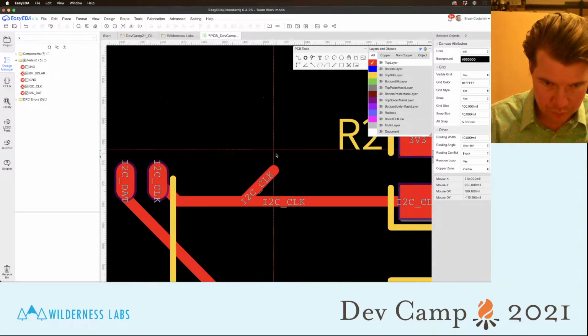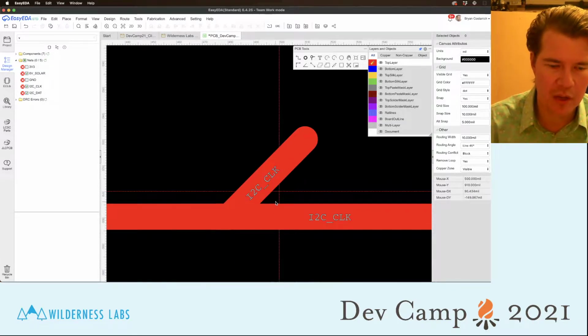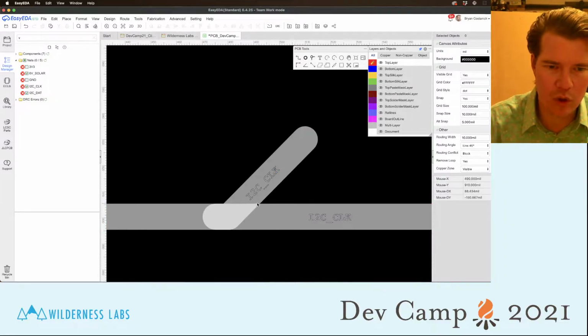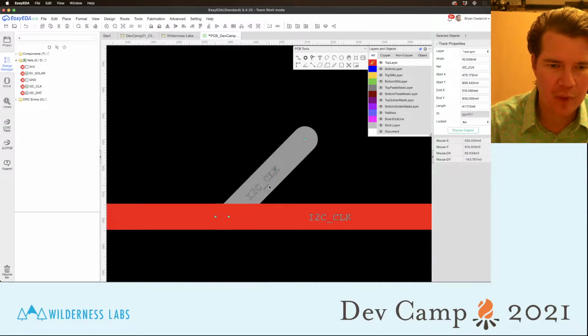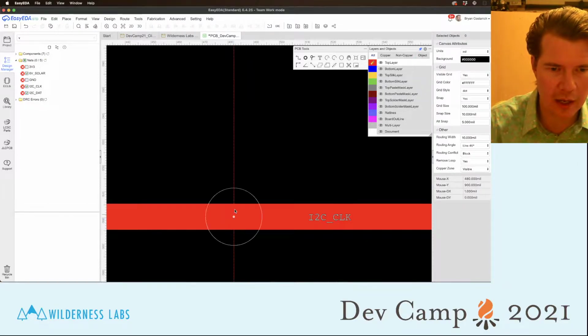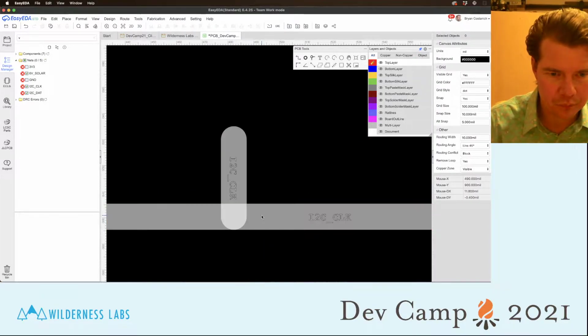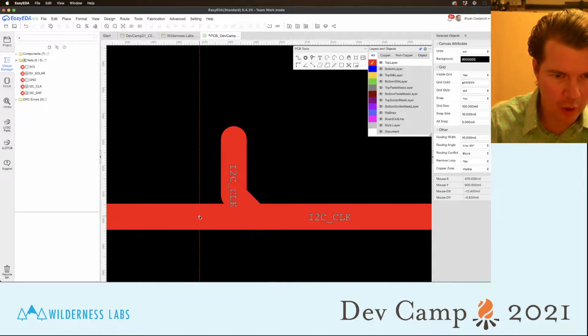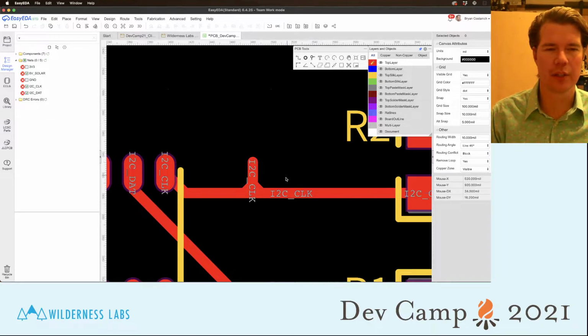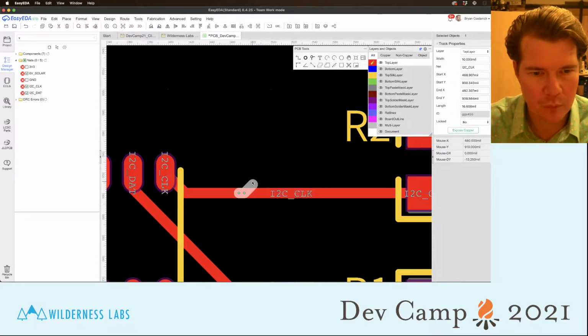And the reason why is that if you're creating this PCB using acid etching, this will create an acid trap in which a blob of acid might get in here and get trapped and etch out much more of this than you want. The best for something like this is to run a line and then help it out with a little 45 on each side, and that's a real clean connection. Obviously, we don't need that here.